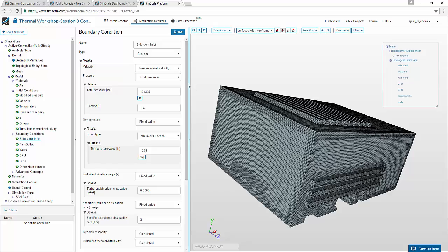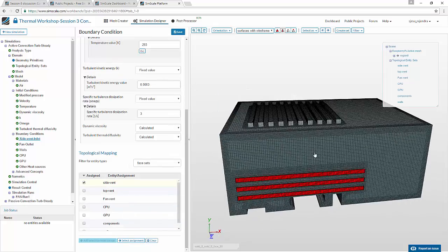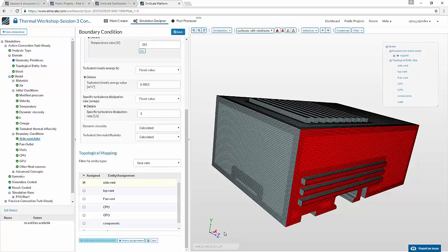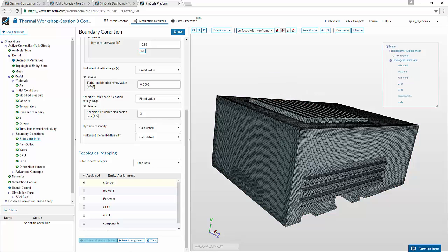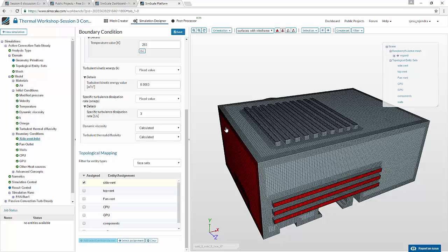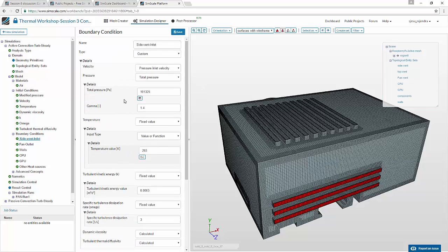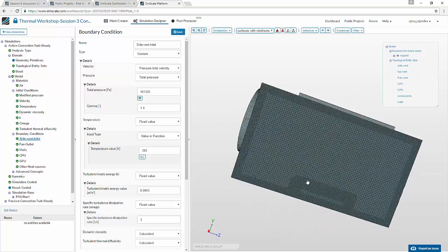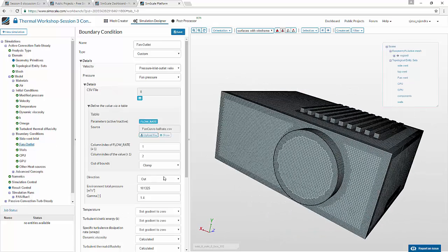For the inlets, in general, this is assigned with the custom inlet, where we only say it is pressure inlet, and this time it is not pressure inlet outlet because we want air only to go into this one. And the top inlets, as I discussed earlier, are completely not used in this particular simulation. So we have inlets in this case and we have an outlet in this direction.